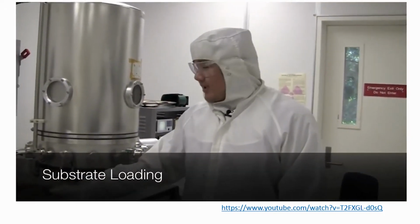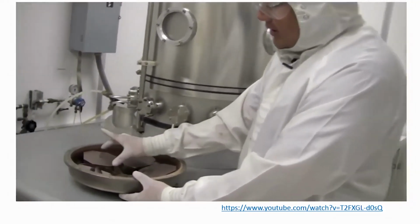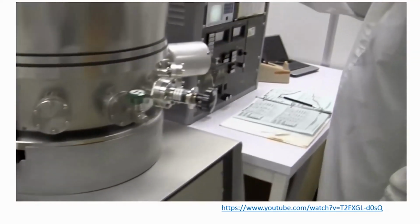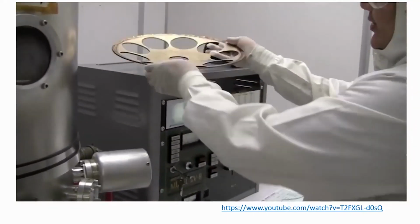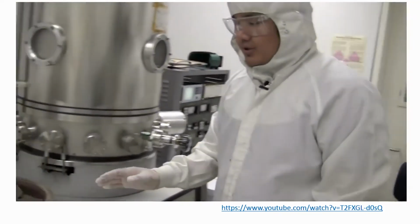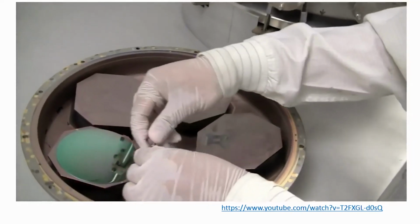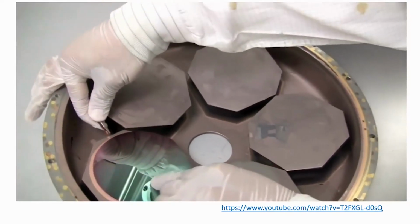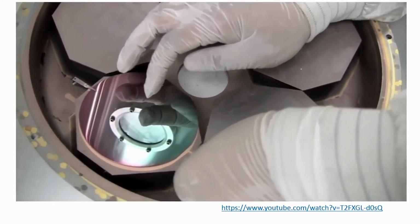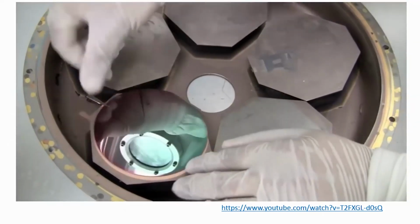This is the phase of loading your samples into the e-beam. There are two types of substrate holders. This one is for whole wafers, while there's another one over here where we can put smaller pieces of wafers as well. And you can actually mount the whole wafers there as well. If you look at this sample holder, we put the wafer on here, and then we're going to clip it onto here. Because this whole thing is inverted in the machine, you don't want the sample to fall. I use clips, but you can also use the thermal Kapton tape.